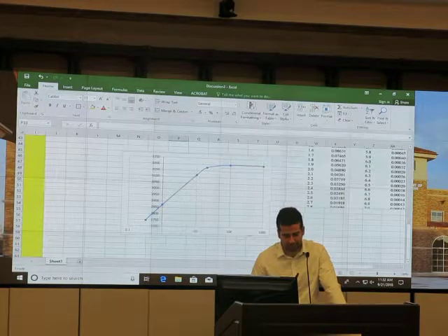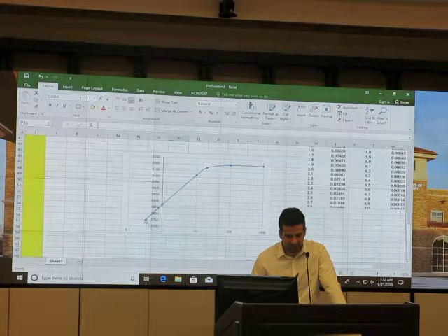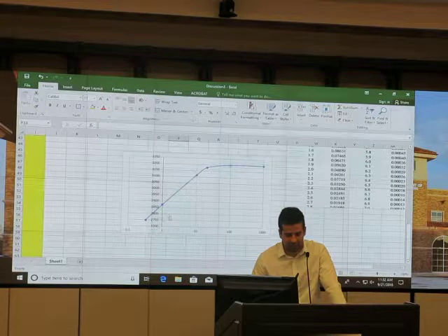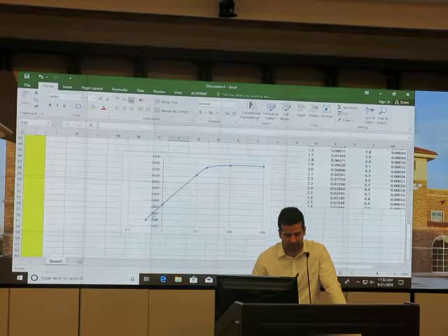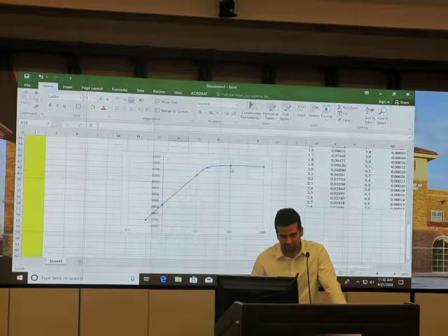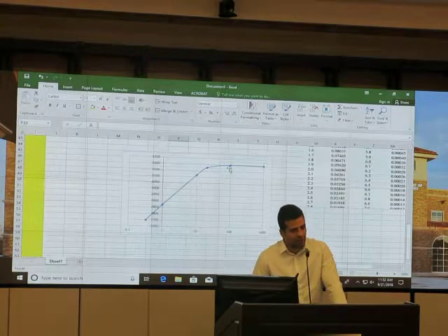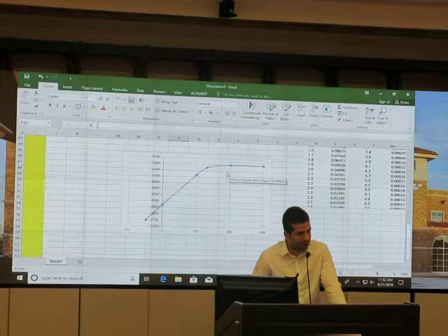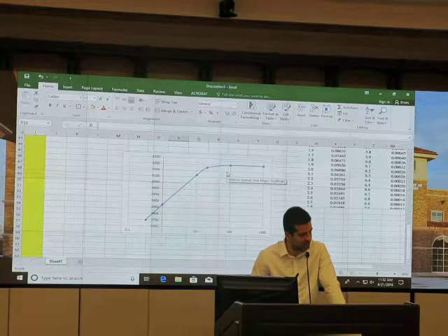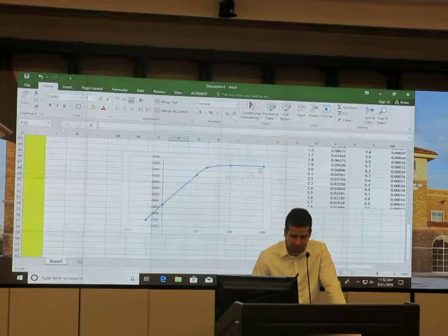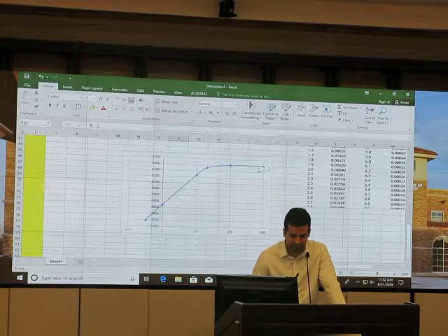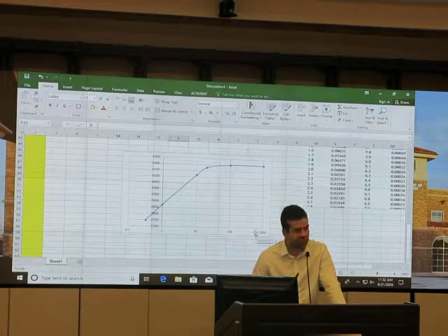Semi-logarithmic plot, and as you can see, this is the well location. At the well location, you have the lowest pressure, and when you go further away from your well, the pressure builds up till it reaches the PI, which already was. So, if you ask, have we reached the boundaries for this case? We say no, because in this case, the pressure wave has not been felt yet. You see over here, the pressure is the same while you go further away from the well.